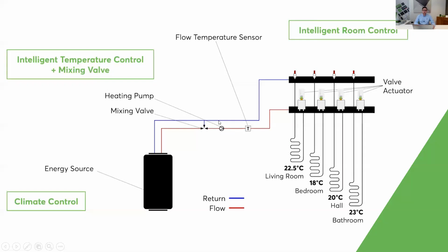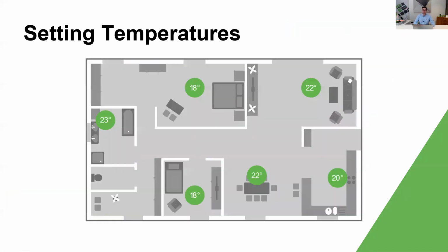Mixing valves will also commonly be called blending valves, so you might know them better as blending valves. They're typically just a twisty dial. You can leave them as that, or you could take them off and put an electronic version in its place, which we could then adjust automatically. And then finally, the climate controller is for the source. So if you're doing a multi-source system, let's say that's heating and cooling, there would be a climate controller for every source of heating and cooling.